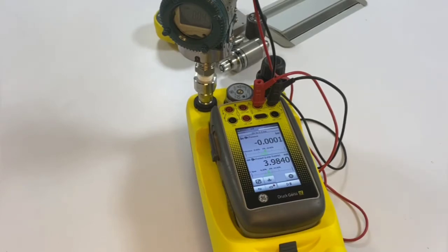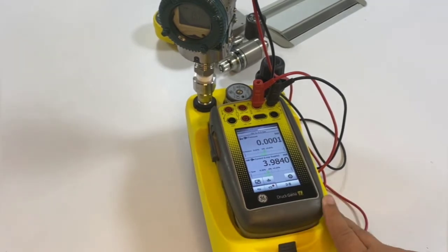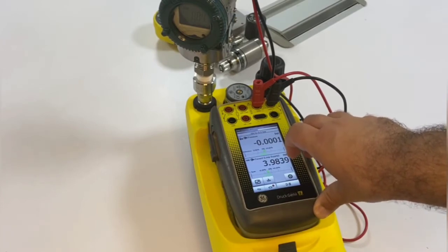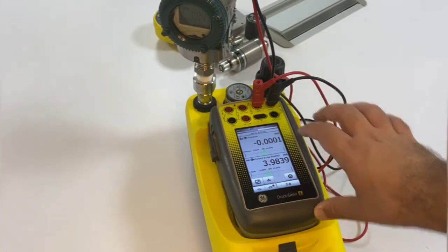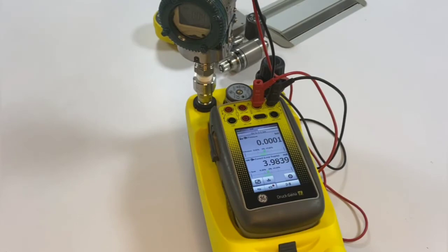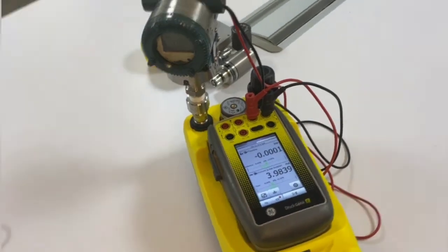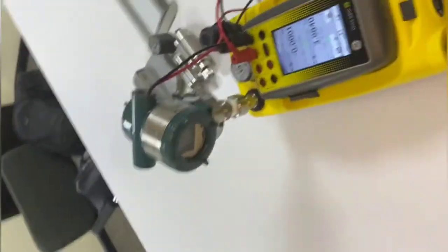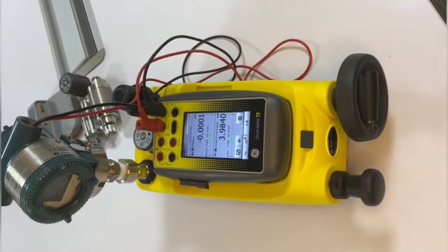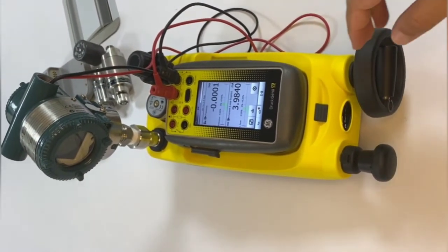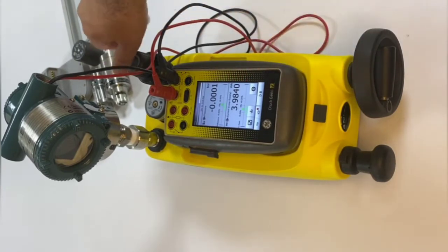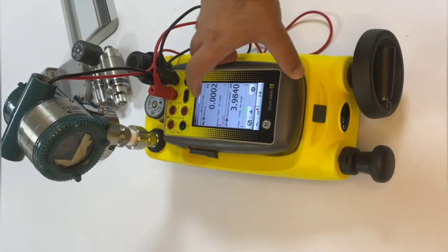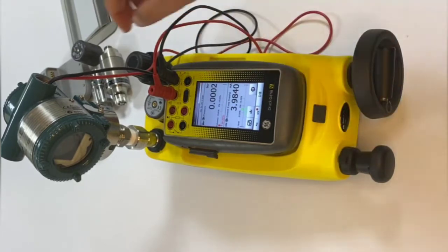So as you can see here, guys, we have the device. The input is pressure, the output is loop. Both have green indicators, means that both are within the limits. Now we will be performing the calibration. So the first point is 0. The set point is within the limits. Save. Now it will say go to 20 bar. So we have to go to the next point.